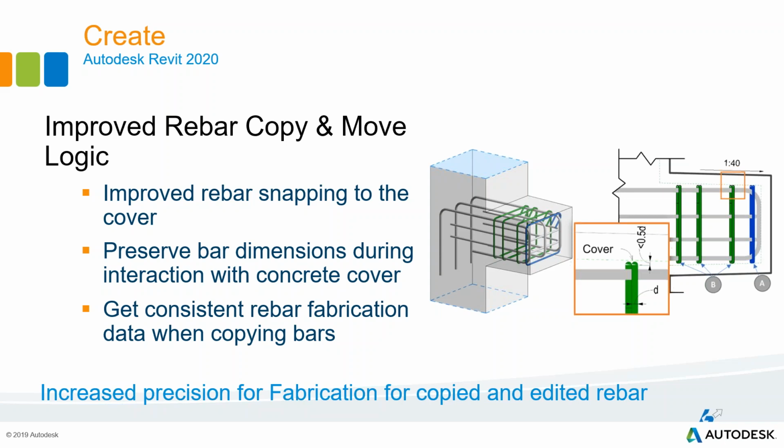Standard bars now snap to stirrups automatically only if the standard bars pass through the stirrups. When a standard and stirrup set are distributed in the same direction, they have parallel bending planes, so none of the standard bar segments will automatically snap to the stirrup segments.